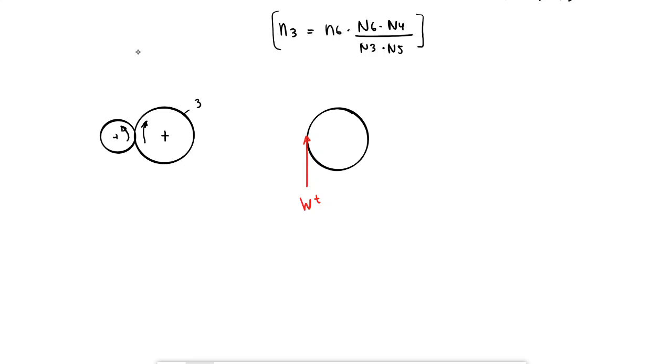But because of how the teeth are made in 3, the involute profile that we talked about, the normal force has to be perpendicular to the surface right here. So it comes at an angle that we call the pressure angle phi. Because this is the total vector, there's going to be a component WT, but also a component WR, radial, going towards the center of the radius. And that's basically it for spur gears.